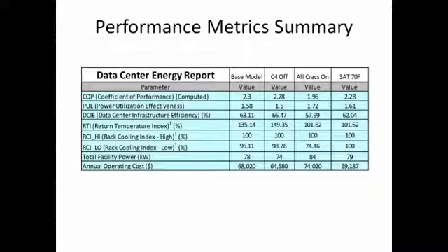It takes about a kilowatt of mechanical energy to dump 4 kilowatts of heat out of the room. DX units can do that as well, if their delta T's are high enough. There's no reason why they can't, but they generally don't. Generally, DX units are run at very high fan speeds to keep the coils from freezing, and as a result, the delta T's aren't very good, and the energy efficiency of them is not very good, as compared to, for example, chilled water.